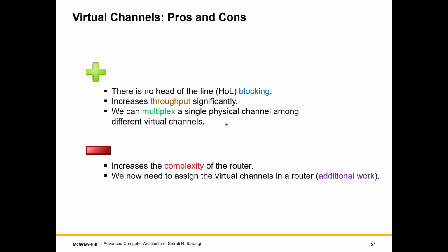As a result, if one of the lanes or virtual channels, known as a VC, is blocked, then packets on the other VC can make progress, of course, if they are going in other directions or if their target VC is free. They could very well be going in the same direction, but taking a different VC on the destination router, which is free.